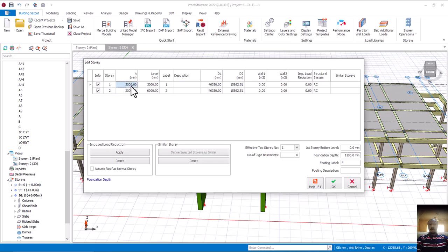Is that okay? All right, I'll come to this place now. The height of this is 3,900. Can you see? So now you might see somebody who is using 3,000 as a normal height of the structure of the building. Maybe G+2, and somebody is using G+2 with a height of 3 meters. Another person also uses G+2, but the height of each floor is 3,900 or 4 meters. You don't expect the two of them to have the same result in terms of foundation or reinforcement.